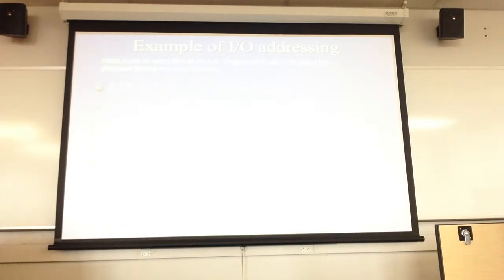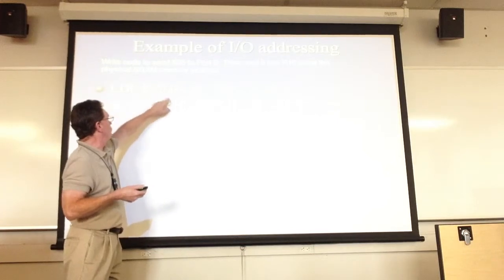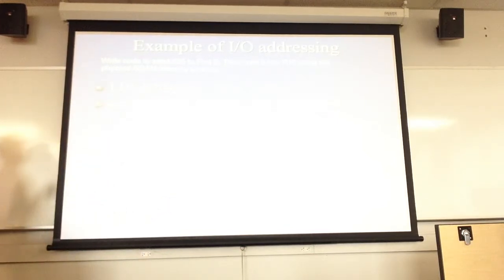Let's see what we got here. Again, we're going to use the I/O addresses. We're going to put an A3 in R20. R20 is going to go into 04, which is the direction register. Put the 55 in, then output, and then store it. And that allows me to just write that thing right there. And whoops, click on the trigger there.